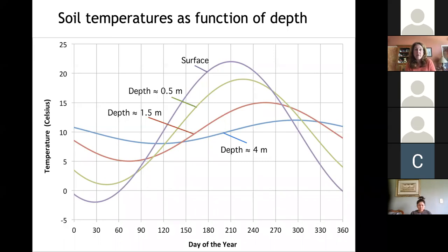What happens is you have more thermal mass. There's two effects, remember that? There's a dampening of the magnitude and there's a shift in the magnitude. So you're seeing that same thing here, that the further down you go, there's both a horizontal shift in when that peak occurs and a vertical shift in the magnitude of those peaks. And that's because the further down you go in the earth, the more effective mass you have. And there's a rough rule of thumb that you get about a week per foot in terms of lag.